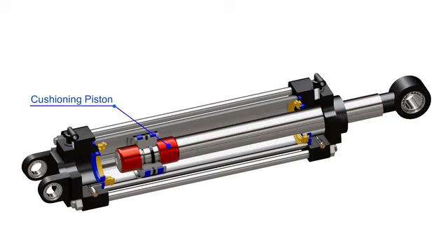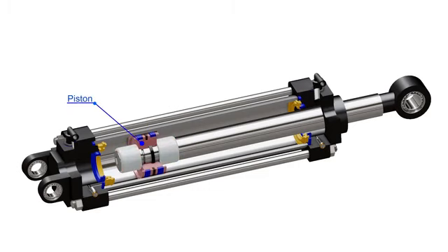Cushioning pistons are assembled with this rod. These pistons prevent any hard shocks at the end of the stroke by enabling the piston to stop slowly and gradually. The piston reciprocates back and forth when there is a pressure difference between any of the two sides. A static seal ensures airtight sealing between the piston and rod. Piston guide rings are assembled to prevent metal-to-metal contact of piston and cylinder. The piston seal provides airtight sealing between the cylinder and piston.